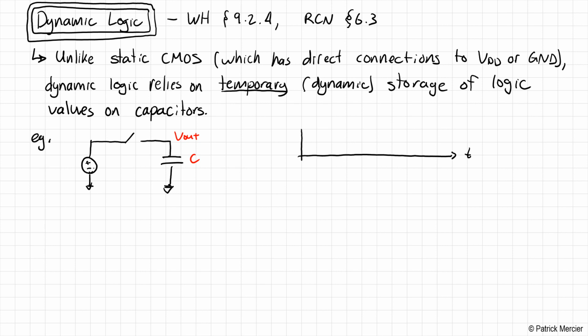Okay, so we have T. This is the position of the switch. If we're drawing a 0, then nothing's happening. And if we're drawing something high, then the switch is on. And then we go back to 0, so the switch is open in that situation. So we say the switch is closed when the value of this logic here is positive or high in this timing diagram.